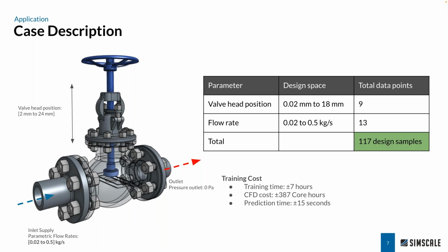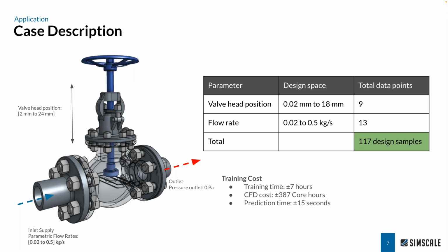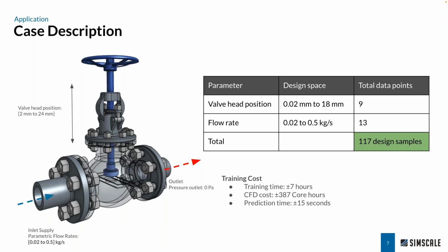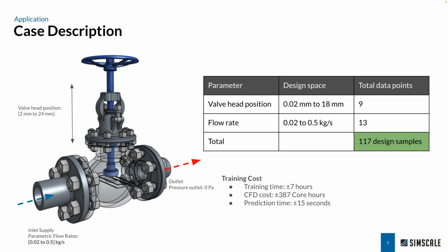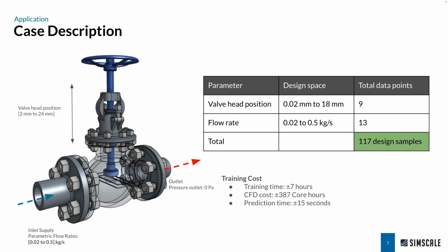It might even go below that if you make a drastic change to the model or the flow conditions. So a good rule of thumb: try to choose the design space wisely before you start the prediction. And if you have one or two cases that you want to predict with AI out of the range, it should be within, let's say, not more than 5% change in the parameter or the flow conditions. I see. Interesting. Okay, that's great.